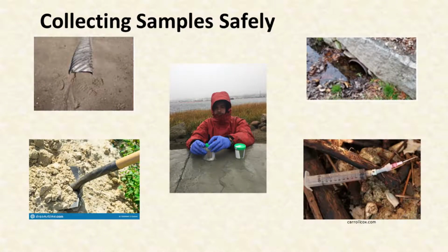It is important to note that if an outfall pipe needs to be cleared of dirt or debris, never use your hands. Often outfalls along beaches or muddy waterways require the removal of sand or dirt to fully inspect or collect samples. The water going through these pipes is untreated and often carries debris from roadways. This debris includes glass and hypodermic needles, both posing risks of lacerations and transmission of diseases. Using a small shovel to clear pipes of sand and debris reduces this potential hazard.